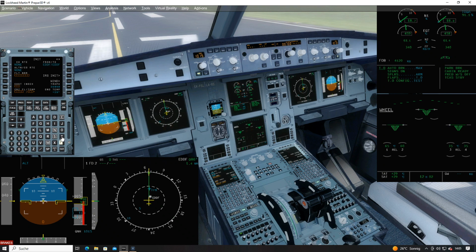The flight number is irrelevant. You can think of anything. We take TUD007. The cost index is a factor between fuel cost and time-based cost. I just put 25 as a random number in here. Flight level today will be 5,000 feet, so FL050.